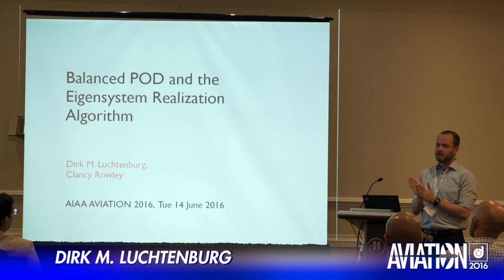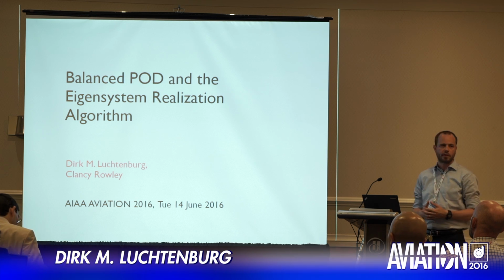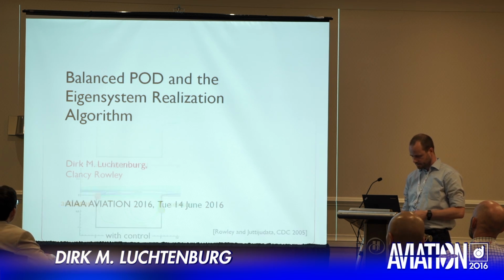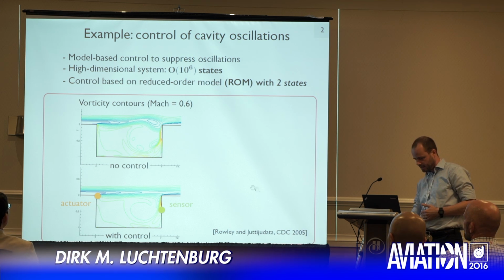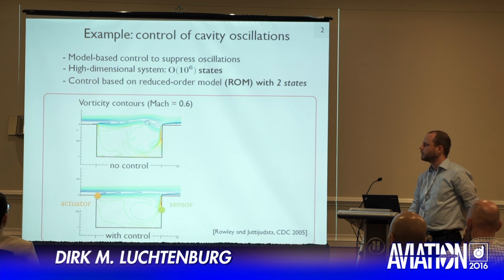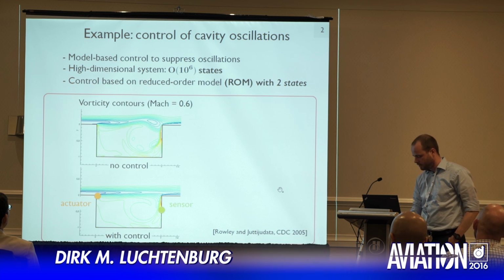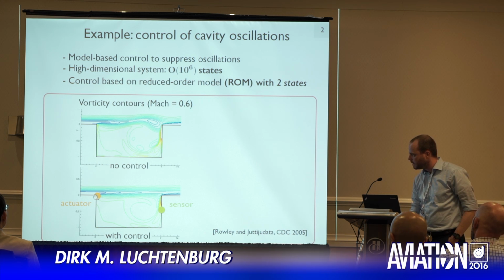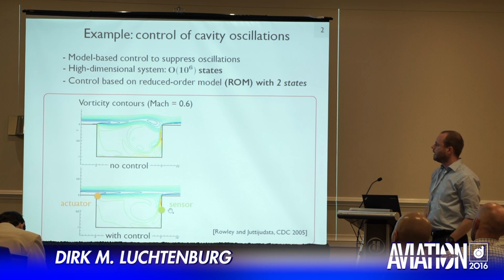So yes, our presentation will be about balanced POD and the eigensystem realization algorithm. Both of these are data-driven methods that we like to employ for active flow control. Here's an example, taken from a paper by Clancy in 2005. We have a cavity flow, and we want to control the oscillations in the shear layer. There is an actuator, implemented as a body force, and a sensor that senses pressure.